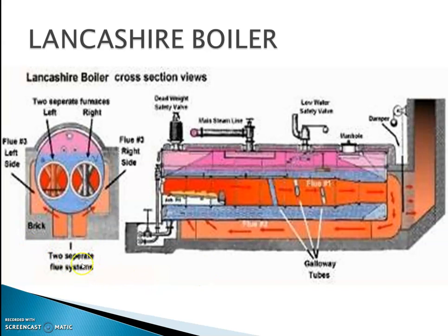The feed check valve sends the water uniformly to maintain the level in the shell. Once the water in the boiler is heated, it is converted to steam by absorbing heat from the flue gas. The steam is stored in the upper portion of the boiler shell. Here the anti-priming pipe separates the steam from the water, and the steam stop valve supplies dry steam for various purposes.